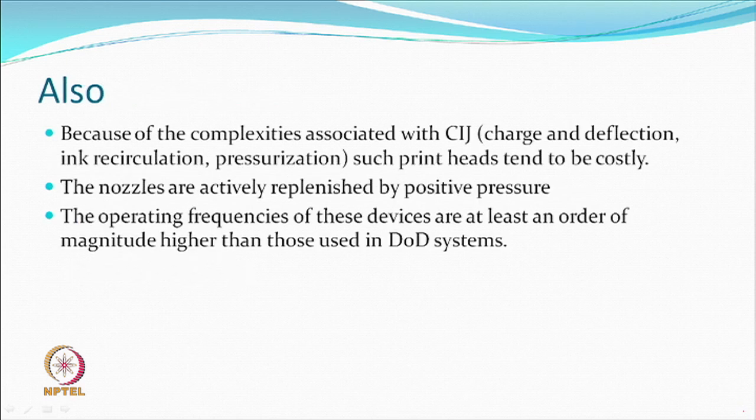And also we learned that because of the complexities associated with the continuous inkjet, charging, deflection, ink recirculation, pressurization, etc., such print heads could be costly.